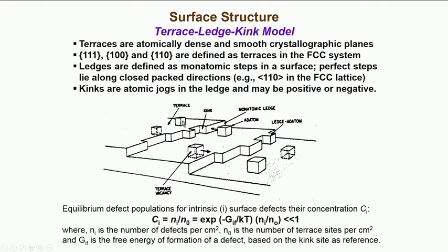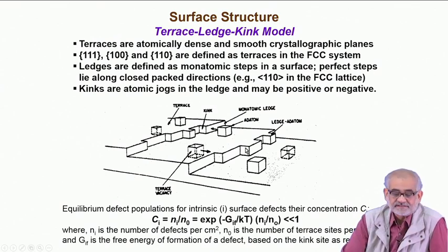So any such jump, where a single isolated atom tries to incorporate itself with an existing solid, will be energetically not favorable, because you are creating more surfaces than the number of surfaces you are annihilating. So a single atom getting attached to a flat interface of an ionic crystal is unlikely.